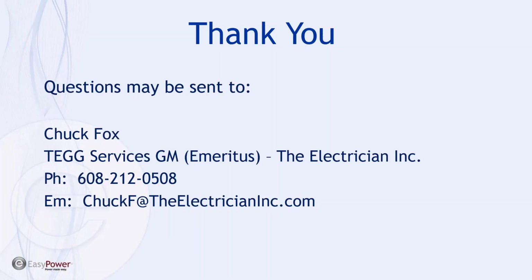The way we look at that is there's basically the energized components, which is the infrared testing, visual inspection, and in higher level equipment, you can also use ultrasonic screening to determine whether you've got some insulation issues or some other types of problems that the ultrasonic tool can pick up as a screening profile. And then there's the de-energized protocols of testing, which ultimately would be torque verification; insulation resistance is a de-energized test, and the protocols there.